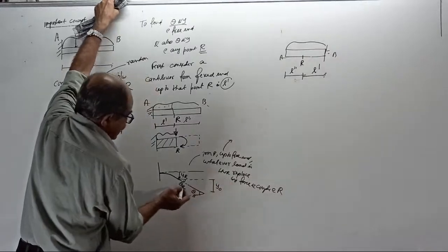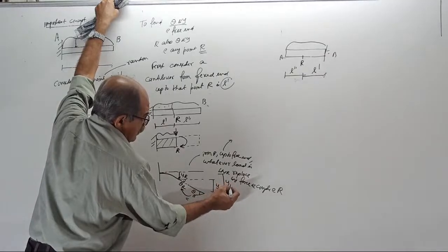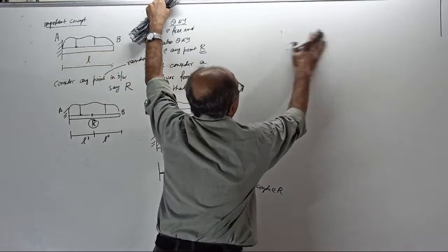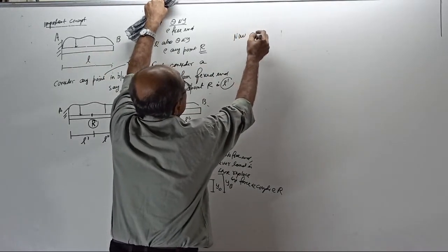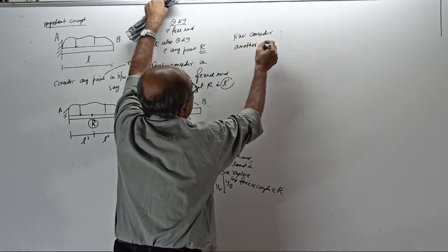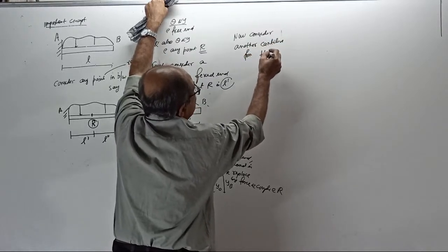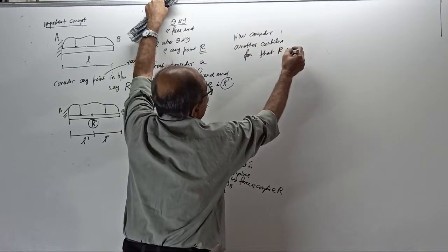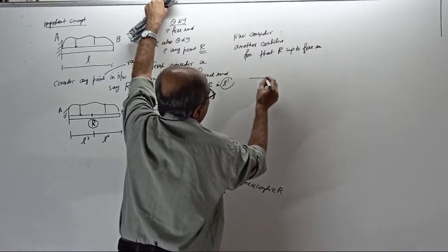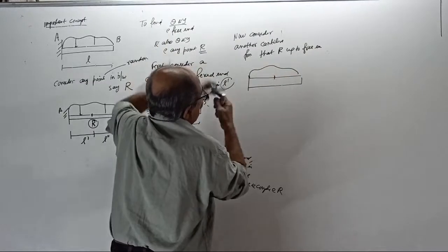So now you can find what? Deflection at R, theta R, and deflection at the free end will be equal to yR plus y naught, theta remains same. Okay. Now what you do is, consider another cantilever. Another cantilever, from that point R up to free end. That is this way. This is the loading. Up to R is already over.